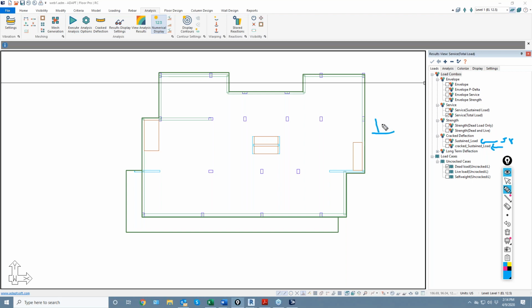So this I gross might be taken down, let's say, to I effective. That stiffness value is then used maybe for the nodes at each element, beam and shell elements. We resolve, and this is the outcome.